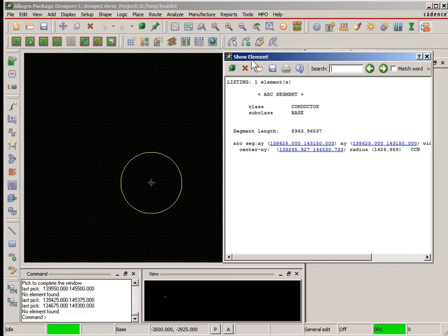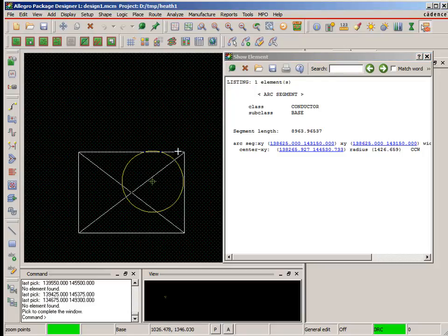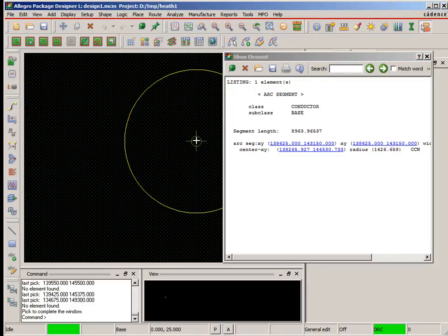And after moving our design origin in the design parameters form, we can see our origin indicator in the user interface, and when we hover our mouse over the center of that circle, we can see that the origin of our design is now the center of the shape that we had imported from the DXF file.